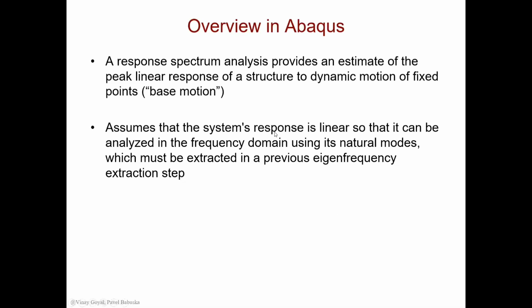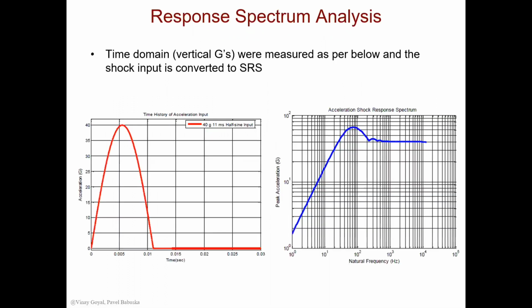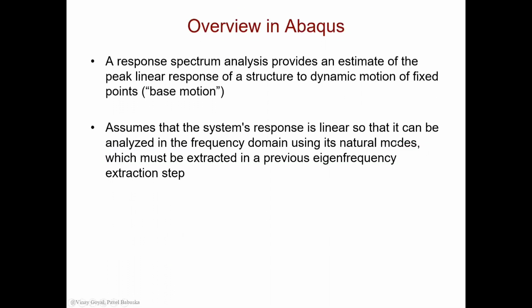So it's very important to first analyze the structure to determine its modal characteristics by extracting the frequencies and the mode shapes of the system. Then we're going to use that information in a response spectrum analysis with the SRS as the input to determine the total response of the system, okay?